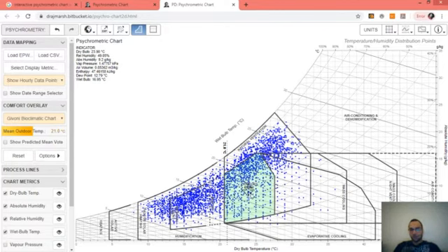by water evaporation within the airflow, and could, for example, achieve a dry bulb temperature of 24 degrees Celsius with a relative humidity of 50%. So the relative humidity increased and the dry bulb temperature dropped. This is the evaporative cooling concept, when you add water vapor content to the airflow, dropping down the air temperature.